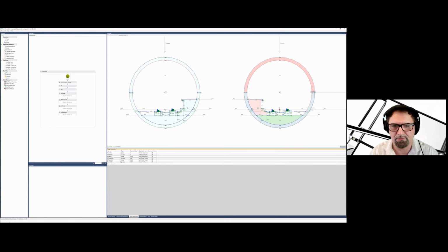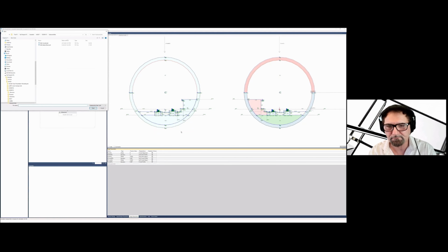Clearly here you can see that I can assign my own names for tunnel center line, and these will later be used when we assign targets for applying them in the corridor model. I'm going to close this subassembly editor. Actually, before I do that, I'm going to show you another file there.